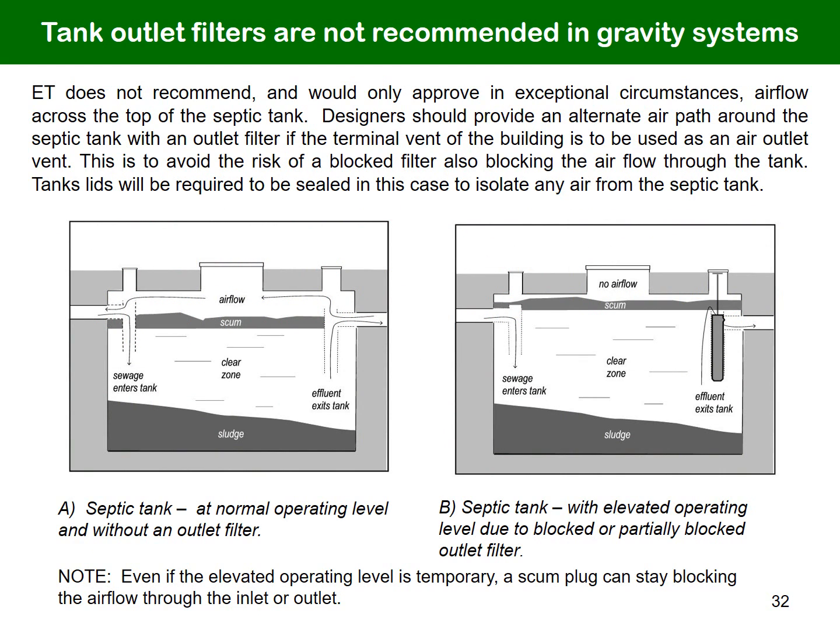ET does not recommend, and would only approve in exceptional circumstances, airflow across the top of the septic tank. Designers are required to provide an alternate air path around the septic tank if the terminal vent at the building must be used as the high-level air outlet vent. This is to avoid the risk of a blocked filter also blocking the airflow through the tank. Tank lids are required to be sealed in this case to isolate any air from the septic tank.